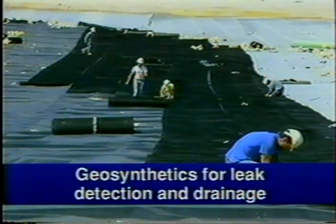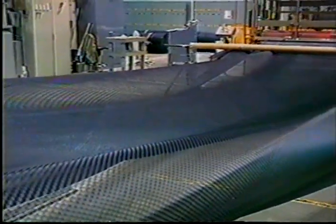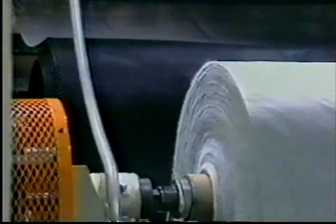Geosynthetics can be used in the primary or secondary leachate collection systems instead of a much thicker layer of traditional sand or gravel. The geosynthetic materials may be geonets or drainage geocomposites. Here we see strands of HDPE resin being extruded to form a geonet. The three-dimensional structure provides planar water flow or hydraulic transmissivity. Geonets can be bonded with geotextiles to form a geocomposite, which acts as both filter and drain.